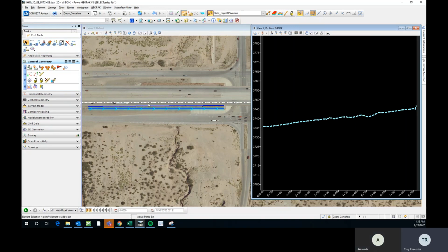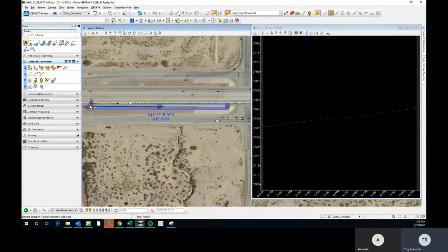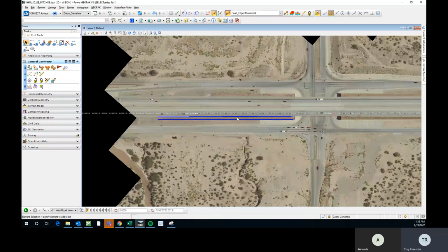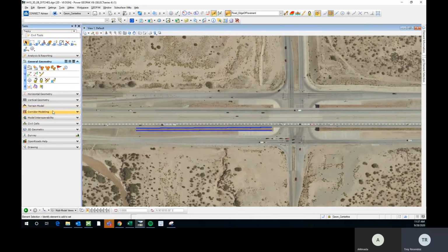These alignments are independent. This line has its own horizontal, and it can have its own profile, and this other line can have its own horizontal and its own profile. Right. Okay. So now we see that we have an active profile there and an active profile here. We still haven't got to why this is here, and we're going to get to it, but the next thing I would do is come to check our templates.